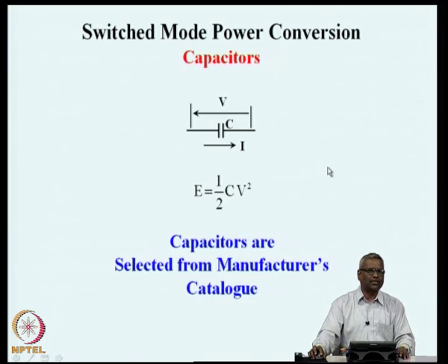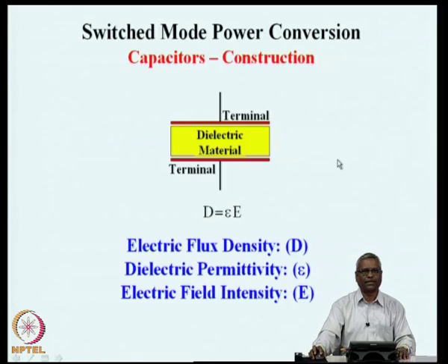Capacitors normally are not designed by power electronics engineers for any specific application, but they are selected from manufacturer's catalog depending on what value of capacitance is needed, the voltage it has to withstand, the amount of energy it has to store, and so on. We will see some of those points here.